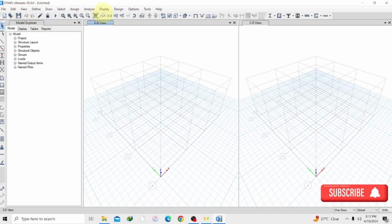We have our menu bar on the top. We also have various tools here that we'll be using a lot in our designs, and I'll be explaining each and every one throughout the course of the tutorials. And by following the videos, watching every one of them, you understand what these tools are used for. Right now we have our steel frame design here. In the case you are doing your steel design, this is where you run your steel design analysis. We have our concrete, we have composite beam design, we have a lot. In other versions, there's connection design here, but in the case you don't have the connection design, you can also find it in the design option.